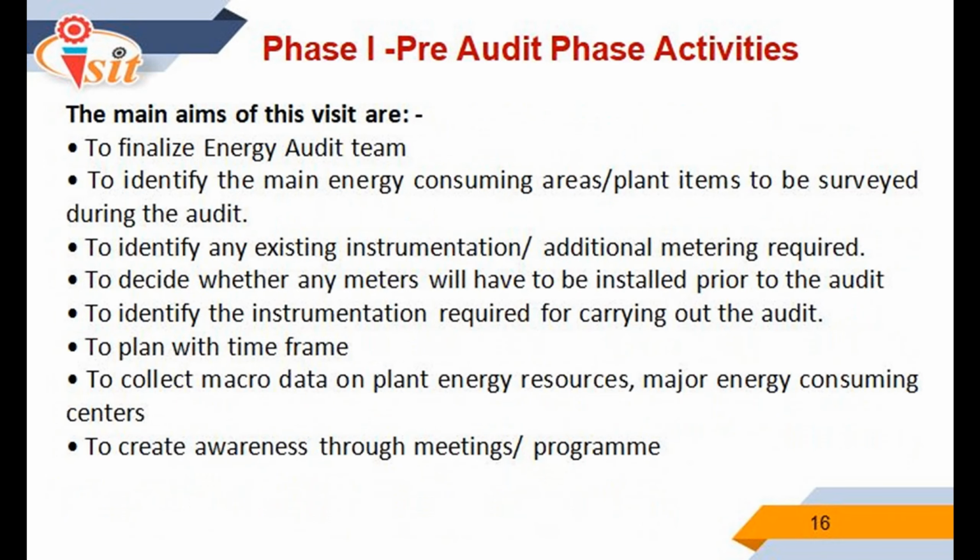The main aims for this visit are to finalize the energy audit team. Second, to identify the main energy consumption areas in the plant. Next, to identify any existing instruments or metering required. Next, to decide whether any meters will have to be installed for the audit for the measurement of different parameters like steam, gas, etc. To identify the instrumentation required to carry out the audit.